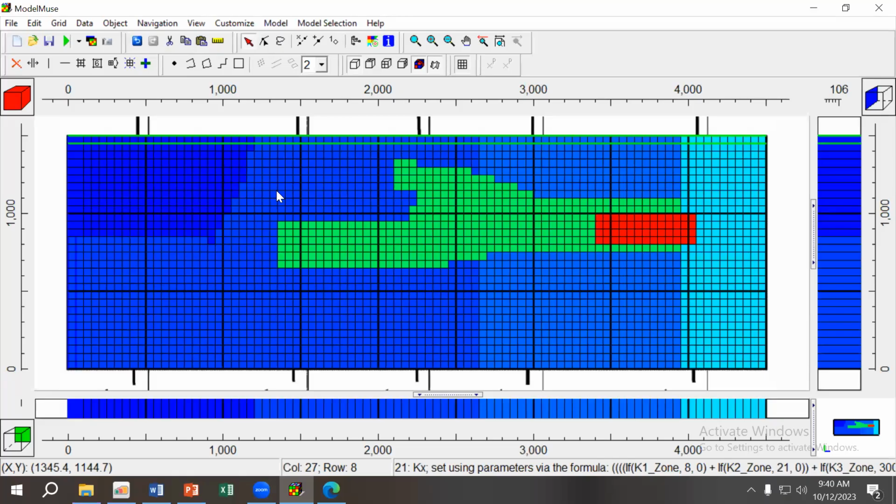So what we have done so far, this is our equation again, for those who came late. This is what we are solving for. MODFLOW will simulate the head, but for MODFLOW to simulate the head, we need to define all the other terms of the equation. So one of these terms is hydraulic conductivity, which we defined here. And again, this hydraulic conductivity, as this equation is showing, changes with x and it changes with y.